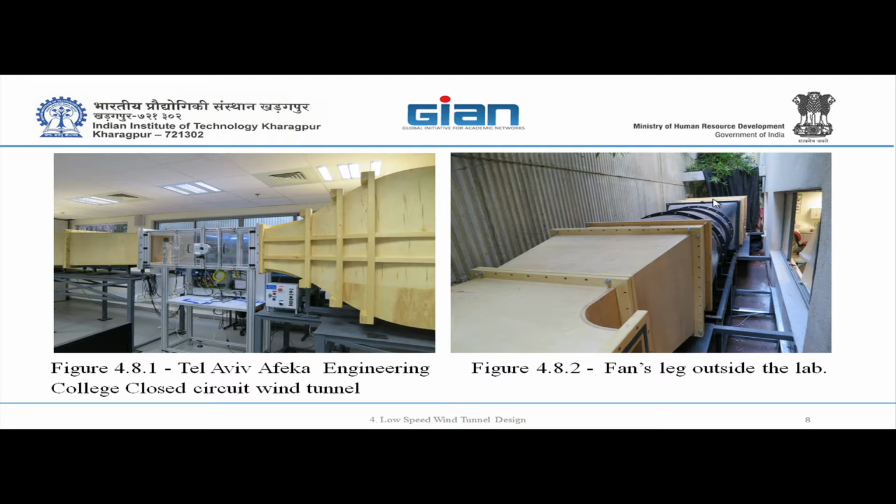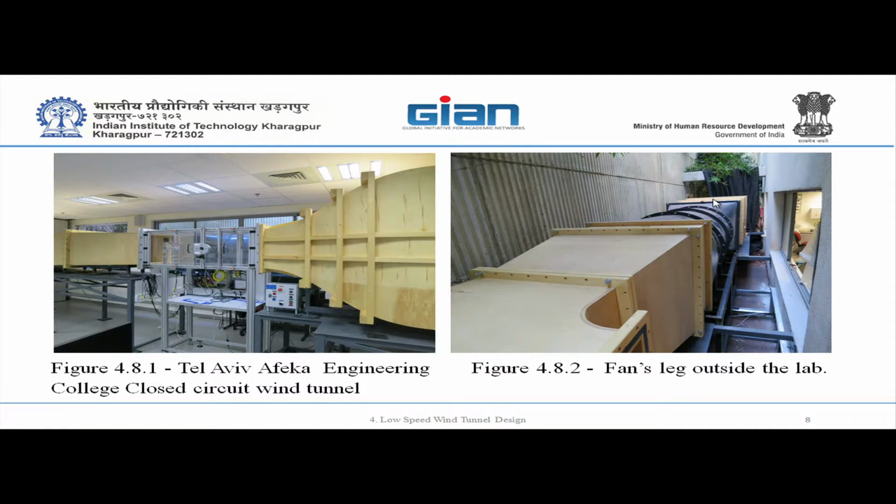So, minimum 2 lengths of the largest dimension of your test section. If it's rectangular, twice the longest leg. But I prefer three times.